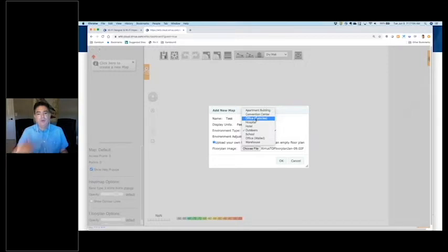And so what this parameter actually does, it's interesting, it will change the overall attenuation expectations of that environment to be less or more. So you can use the tool and get very specific and draw walls and model the building exactly, or you can do a higher level approach and say, I'm not going to get into all those details. I'm just going to say the average attenuation there is akin to an office or an apartment or a warehouse. Obviously in a warehouse, less attenuation, open spaces. Walled office is going to be a lot tighter because the expectation is that you have walls around every single office. A hotel, even tighter most likely in terms of the space available, or perhaps similar.